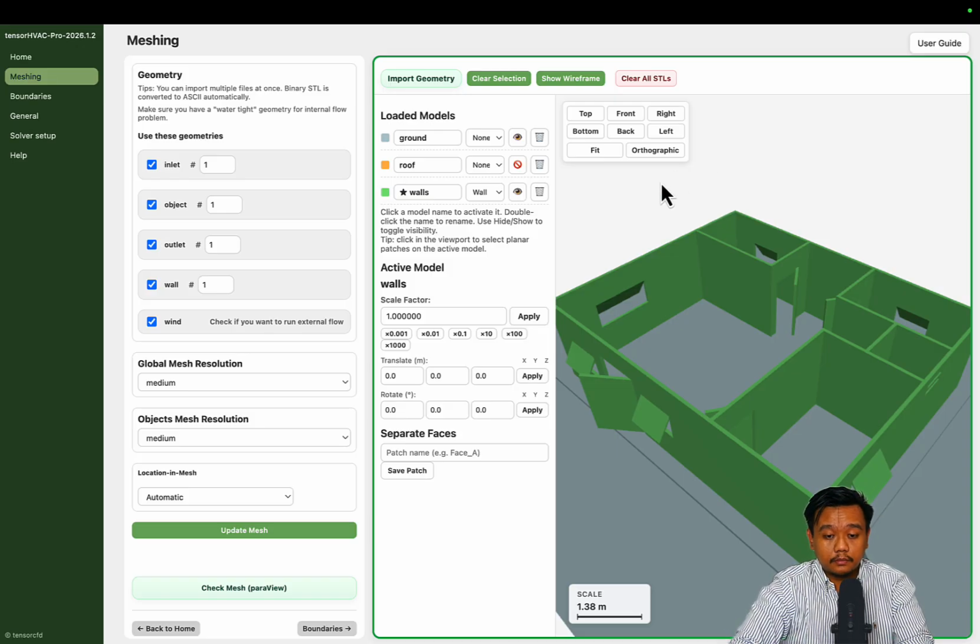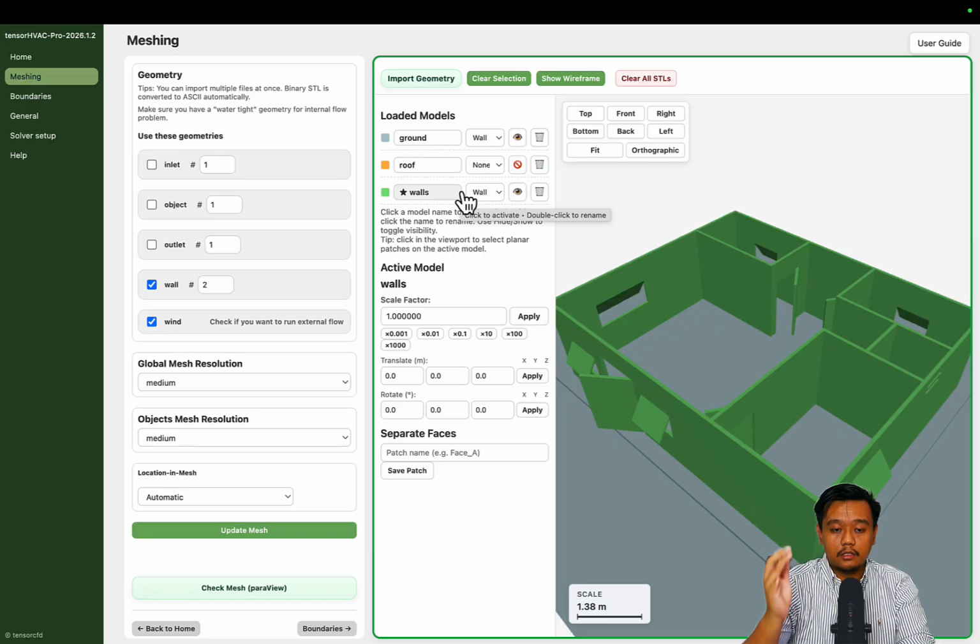traditional CFD software. Okay, here we have selections for the boundary conditions. Inlet and outlet are basically used for things like an air conditioning unit, like the diffuser, but in this case we don't need the inlet and outlet. You can check other tutorials to use these boundary conditions. And objects are basically used for things like a human body or maybe some chairs or tables with small details. But here we will just use the wall, which is for a flat surface like the ground or maybe the roof, or these side walls. Okay, so let's set everything to wall.